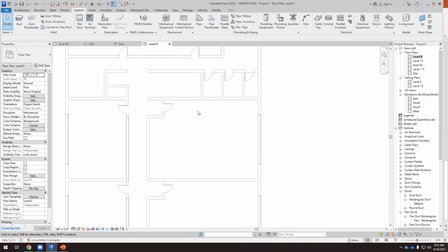If there is a room and people are here, and this is important, the height, and I haven't checked the height of this, but the height of the room compared to the height of people, it's important. We have an occupied zone. So this can be 7 feet maximum. This is what we call the occupied zone. So comfort has to be here.